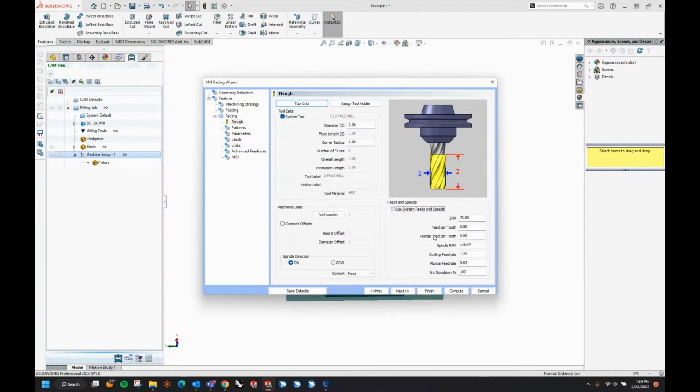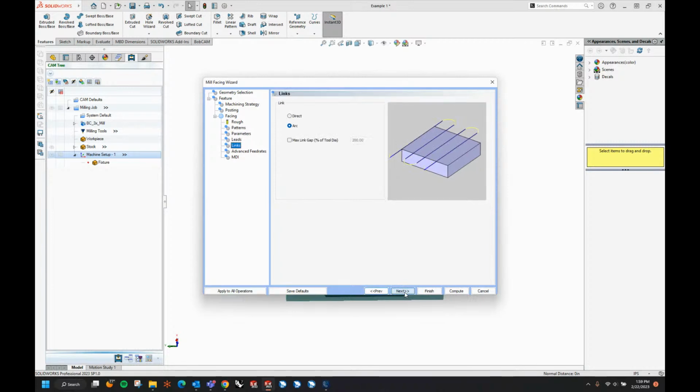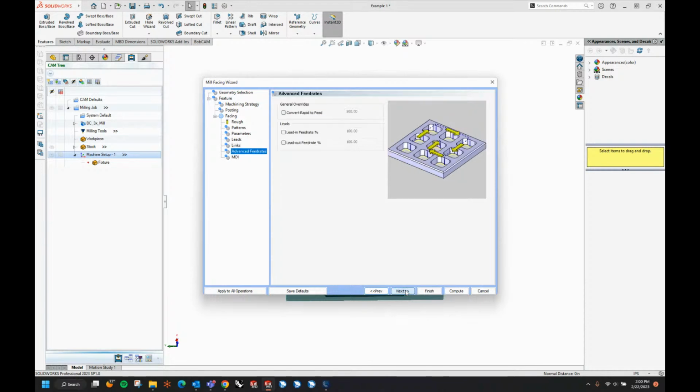So if I say my cutting feed rate, and let's just use a basic number, 100. If my feed rate is 100, when I go to those radiuses, I might want to increase that 500%. So if I do a larger number here, when I go to actually post my code, because I have arc turned on, it's going to do a faster feed rate for those radiuses than the line moves that are actually cutting, kind of in a way making a rapid.